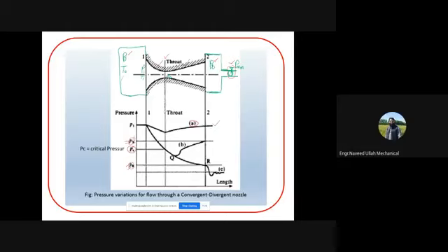So you see that if the back pressure, this pr, is less than the critical pressure, this is your under expanded case, which we call C. Expansion is there down to this point, but you have this PR that is less than PC.